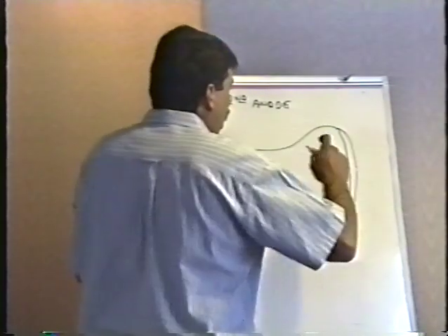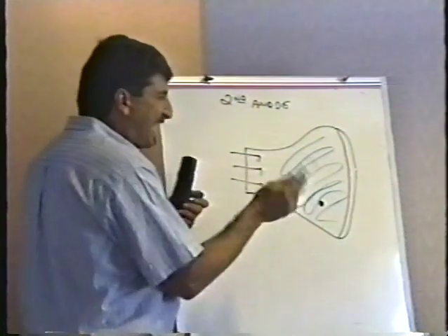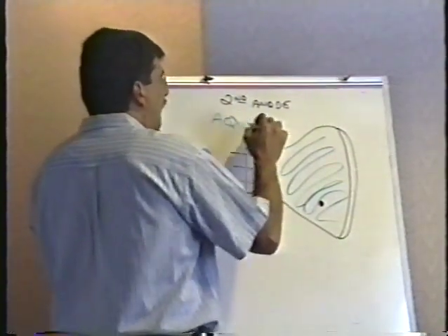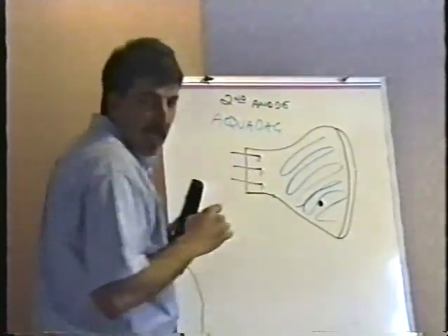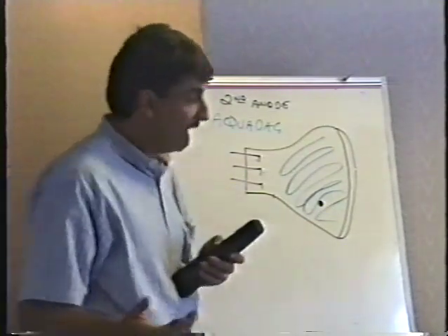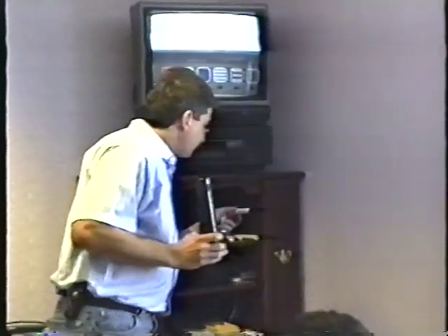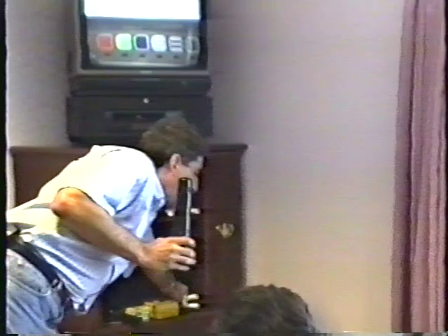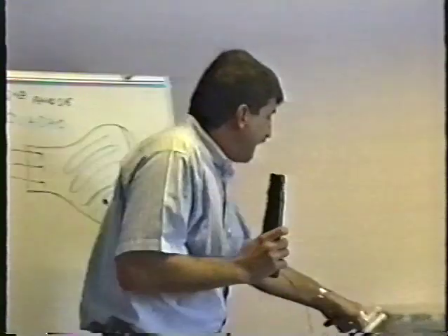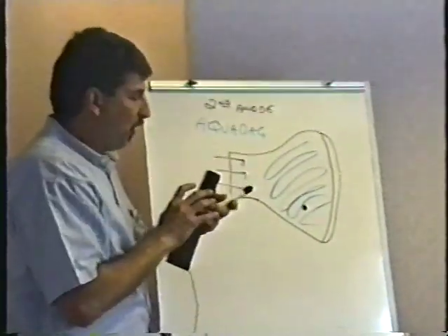All right. Also, coating the whole inside of the glass bell of the picture tube is a metallic paint called Aquadag. I have no idea why it's called Aquadag. It's not wet, so I really just have no idea why it's called Aquadag, but it is called Aquadag. Anyway, the Aquadag coats the whole inside of the picture tube, meaning that when I connect something to the second anode of the picture tube, I am actually electrically connecting to this whole Aquadag on the whole inside of the picture tube.